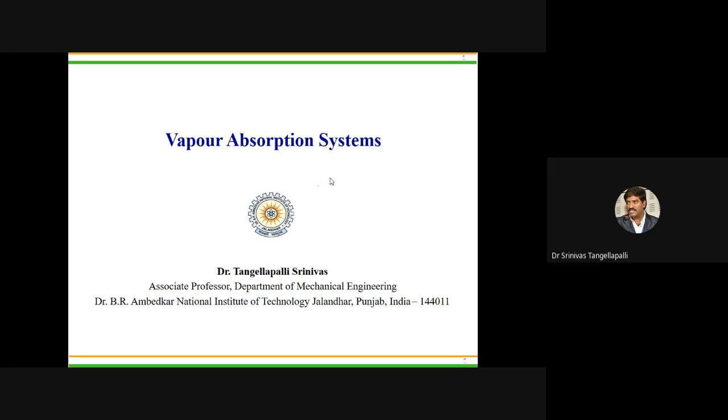What is the alternative option? The ammonia water mixture is the best option, the best working fluid compared to other fluids. Water is the ideal fluid in all applications, especially for the thermal power plant. So the ammonia water mixture is good for low temperature applications below 0 degrees centigrade, such as cold storage, refrigeration and similar applications.